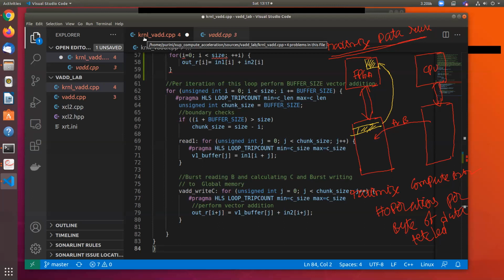And I think there is a lot of traffic on the chat also about how much memory you have. So Sampath's point is correct. Memory inside the FPGA is limited. But whatever you put in the memory inside the FPGA can be accessed very quickly. So if you wanted to parallelize, you would bring memory to the FPGA, run a lot of kernels and do computation on that, and in parallel transfer more data from the DRAM to the FPGA, because that is time consuming.